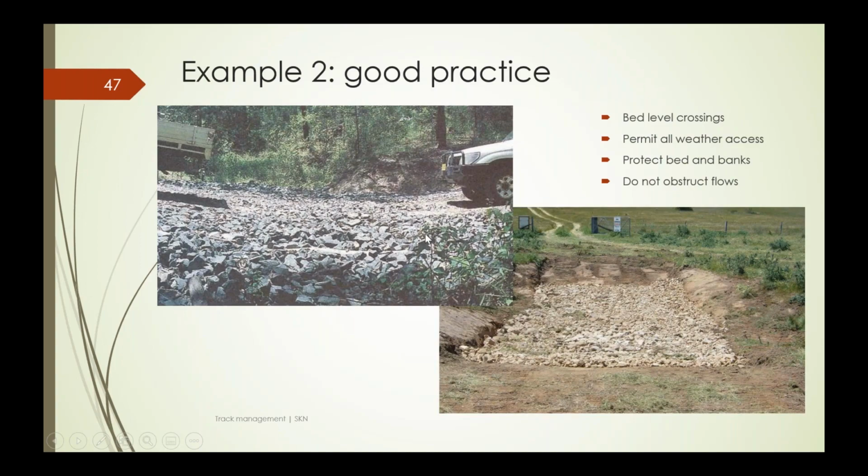Good practice. This again is what we call our bed level crossings. So we've got rock reinforcing of the bed and the approaches. We've got no obstruction of flow, and we don't have the problem where with culverts you have soil piled over the top and the problem of water dropping off the edge of a culvert and washing out the fill batters.